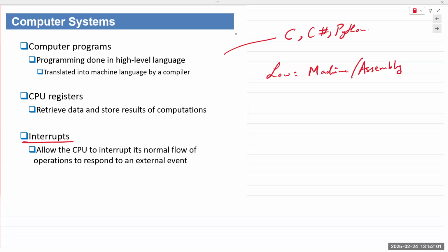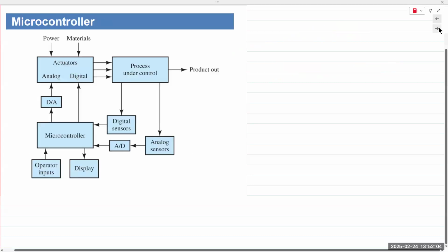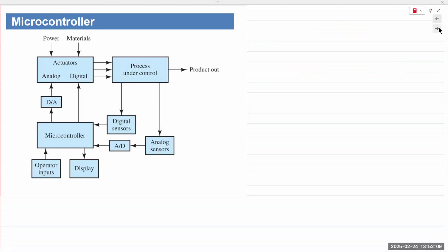All right, so that's a CPU, computer. Then there is a microcontroller. Microcontroller, unlike a CPU, has a CPU, but the processor integrates some memory and some storage inside it. Even some I/O addressing lines inside it. And so a microcontroller is a scaled down version of a CPU, but it integrates a bit more than a CPU inside it. And microcontrollers are designed for one specific function.